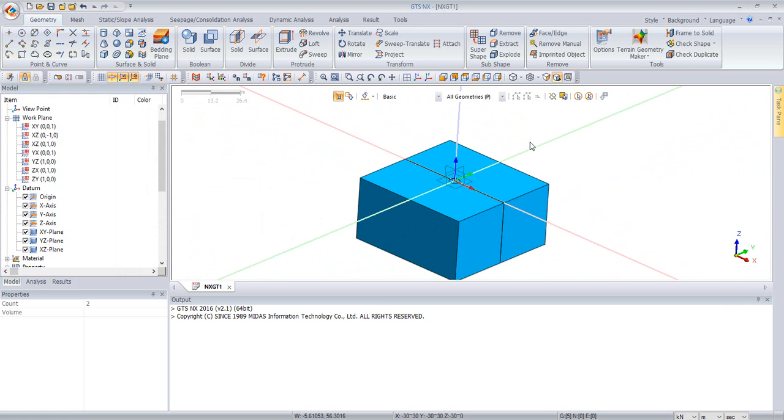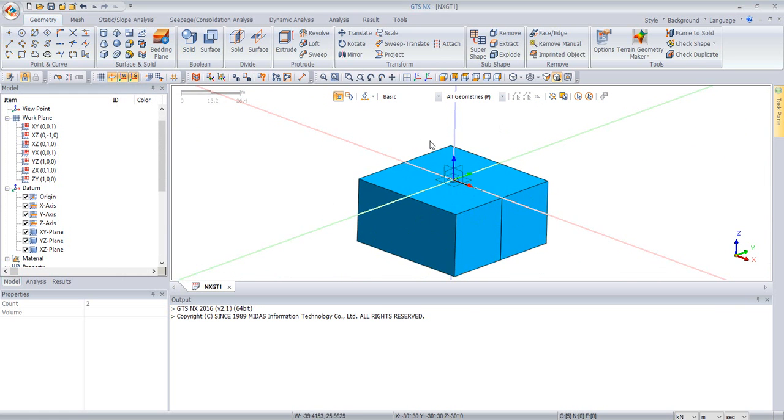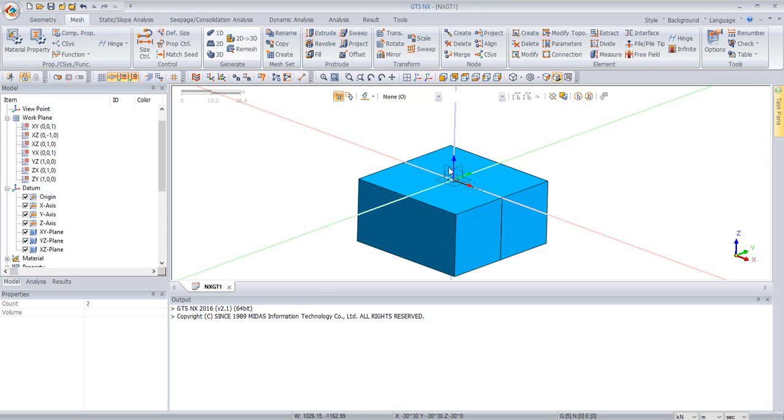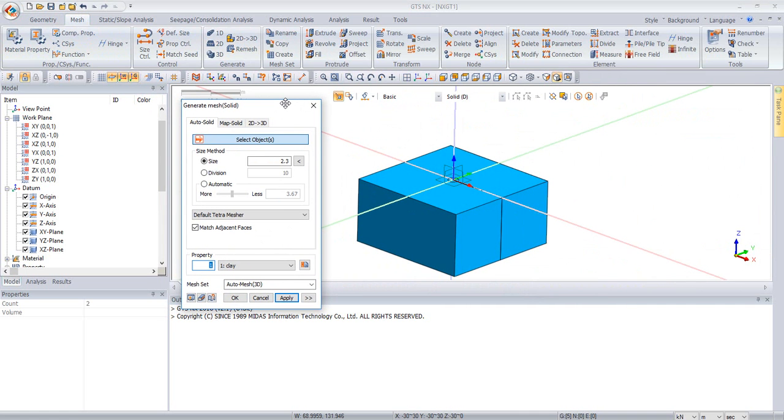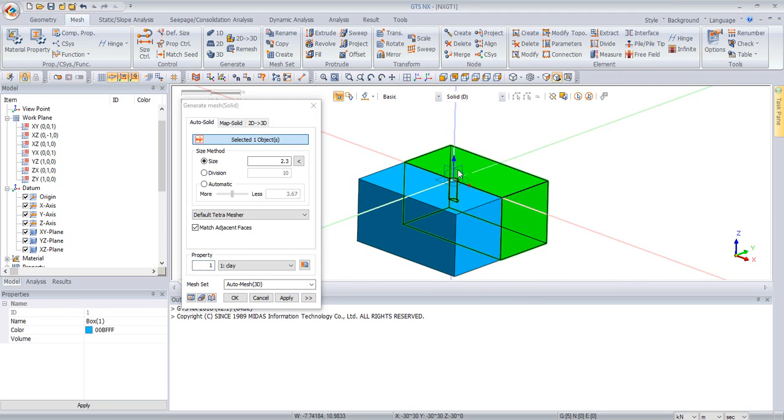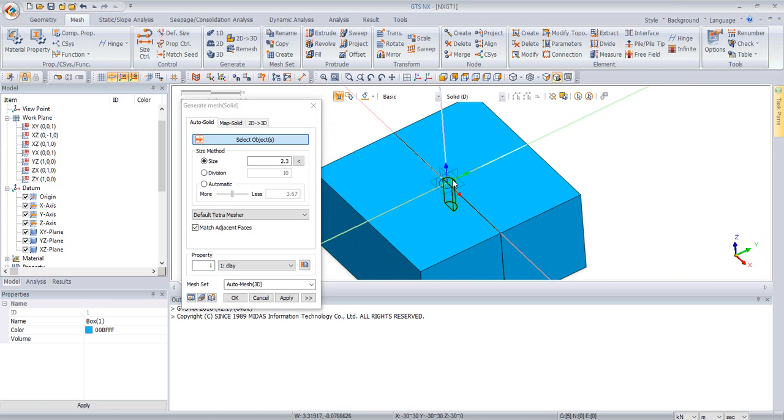As of now, everything we're going to mesh is going to be with the clay material because they're all 3D objects. Later on, we're actually going to also mesh the 2D pile faces, but as you may know, suction piles are actually hollow inside and they don't have a bottom face, only a top face. So we'll show later how this is achieved when we're trying to model those kinds of geometries. For now, let's focus on the soil only, since the inside of the pile itself still only has clay, so we will be meshing this cylinder as clay, and we'll just call it inner soil.